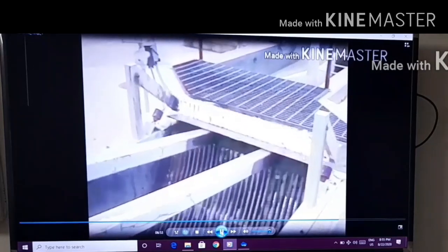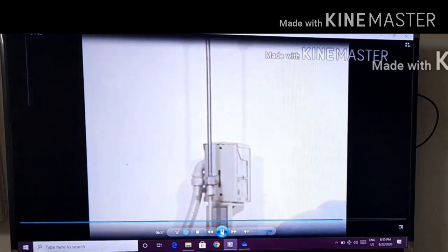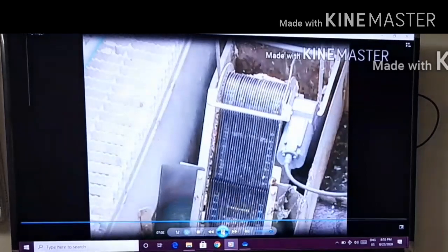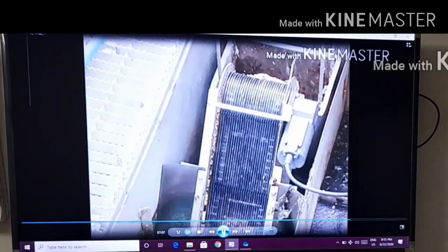There are many types of mechanically cleaned bar screens. Some screens work with a continuous chain and rake mechanism that loops around and cleans the bar screen. Some bar screens do not have any submerged bearings or chains and are cleaned with a long arm or a raking mechanism. Another type of mechanically cleaned bar screen is called the arc screen. This screen gets its name from the arc shape of the screen. Most mechanical screens are triggered by some type of automatic device that signals the unit when head loss through the screen increases. Automatic devices could include float switches, bubbler controls, and ultrasonic devices. And some mechanically cleaned screens are controlled by a timer.